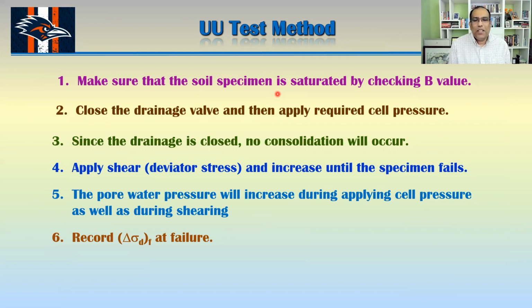The pore water pressure will increase while applying the cell pressure as well as during shearing. And record the deviator stress at failure. Okay.